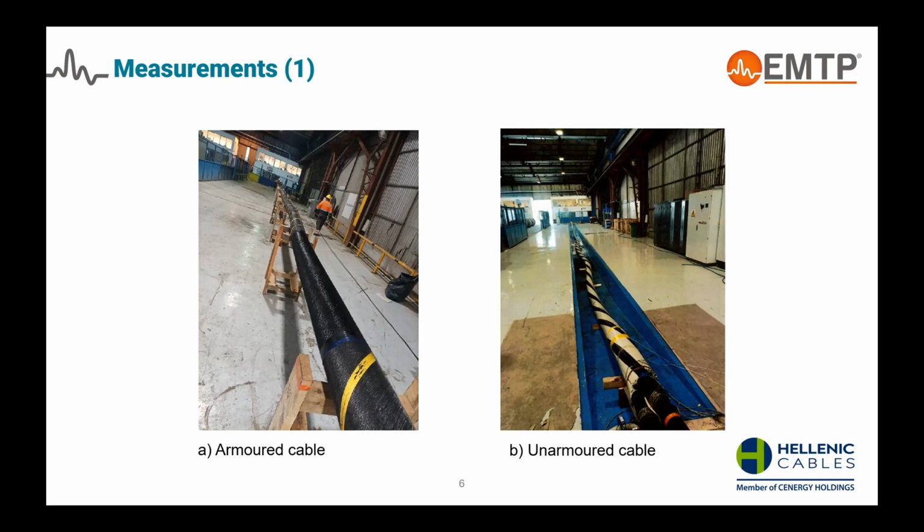In the first picture, the sample is placed higher from the ground in order to avoid interference with the metallic reinforced concrete. And in the second picture, a special corridor is implemented, which is free of any metallic element, and is constructed this way because in the next step, we could measure this as a wet condition cable, and the corridor will be filled with salt water.